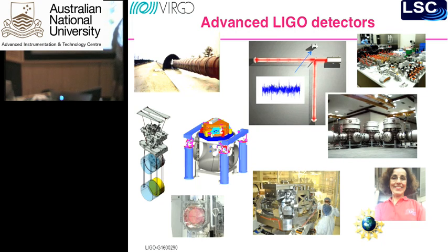And then those are suspended on these piers, right here, these beams, and these beams are each connected to the piers with more 6-axis actuators for the final stage of isolation. So that's 3 stages of active isolation and 4 stages of passive isolation to get the displacement noise below 10 to the minus 18 or 10 to the minus 19 meters.